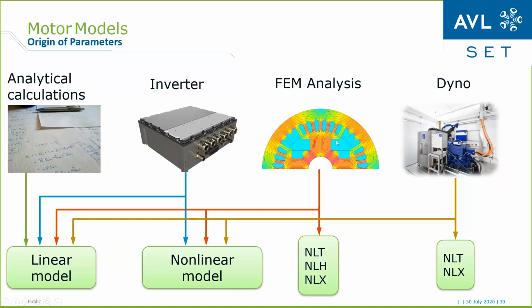With the finite element analysis, it could be possible there will be a variation with the actual motor. So in order to validate that, once the said motor is designed, one can connect it to a dyno and start extrapolating the model data again and cross-verify it with the model data which was acquired through the analysis.